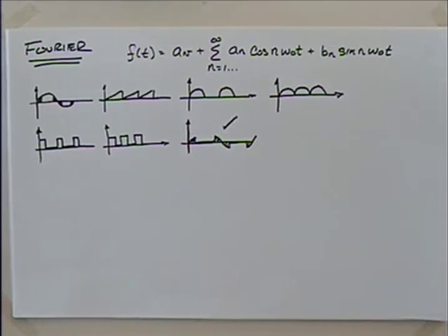This is really a big area in motor control. If we think about taking an AC motor, when you turn an AC motor on, it's just full on, and when it's off, it's full off, which can be kind of hard on mechanical components. So really in the last probably 25 years, motor controls have come online, where we'll start to ramp up the motor speed. We can control the signal into it. We can control the frequency. So we'll start out with a nice soft start.